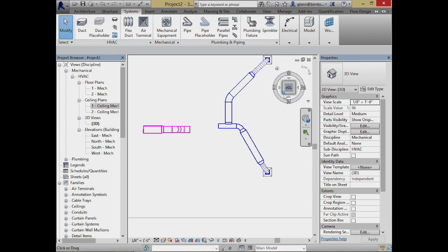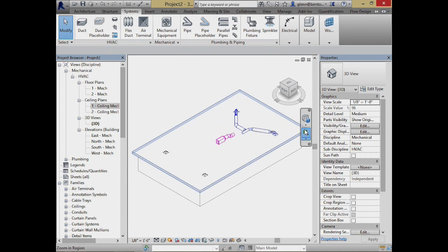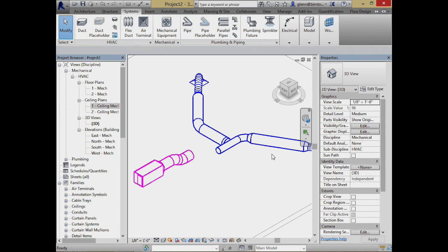A couple things we'll do next time will hopefully make it make a little more sense in terms of playing around with the sizing here. We are going to connect them together on the supply side. We're going to connect them together on the return side. And when we have a complete system, we'll see how it can help us compute the total amount of space going through there and what the cubic feet per minute is, to help us size these things so that ultimately it'll help us figure out how many of these terminals we need as well as what size all these ducts should be.